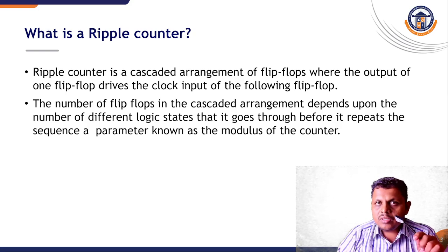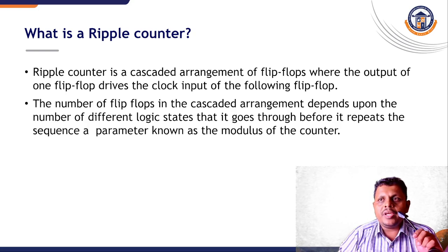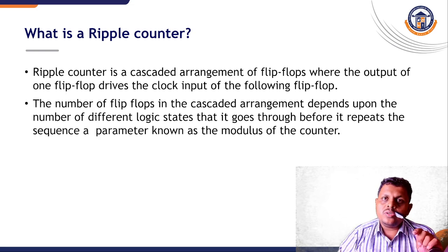Next, we are going to discuss ripple counters. A ripple counter is a cascaded arrangement of flip-flops, where the output of one flip-flop drives the clock input of the following flip-flop.